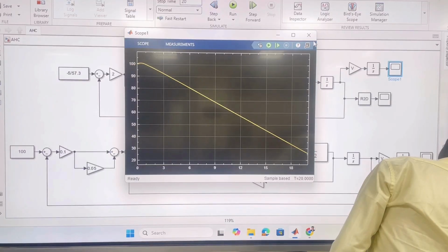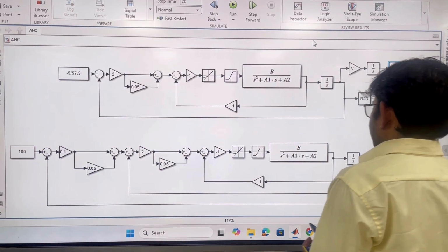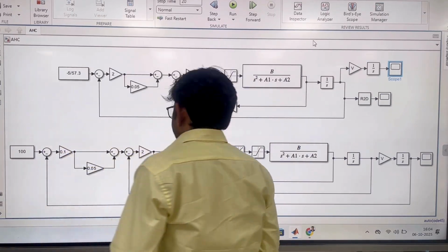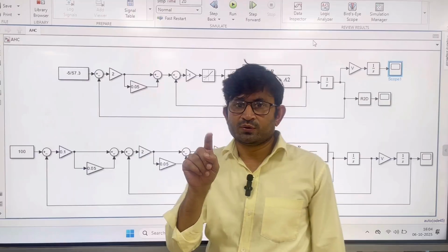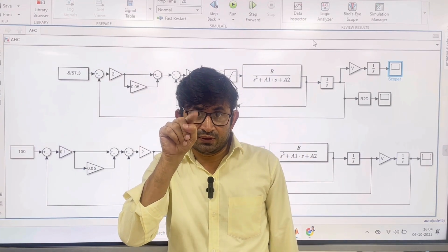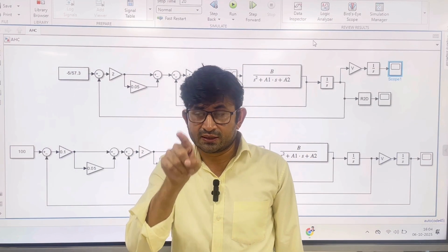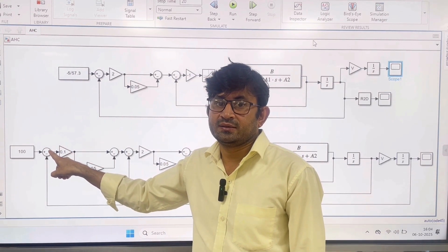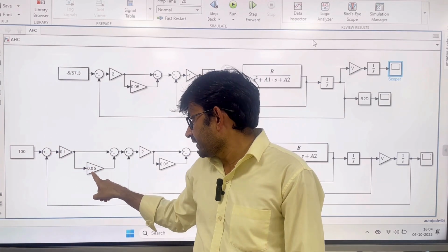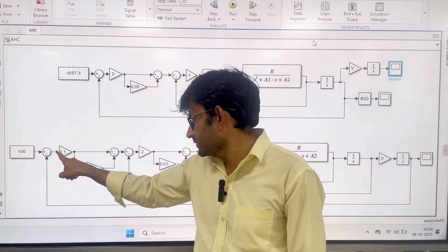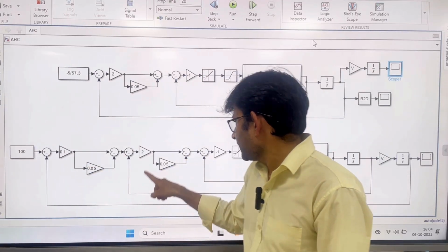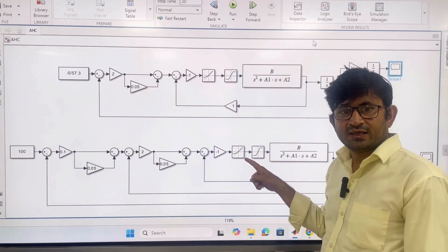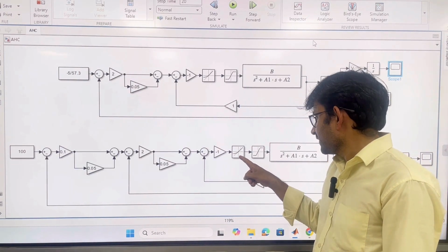What we will do is take a feedback and close the loop here. I have explained in the theory the PI block, proportional integral. This is P, and with respect to that P, I am taking 5% of P, which is combined into this PI. Here also PI. This is a physical limit, position rate limit and position limit.